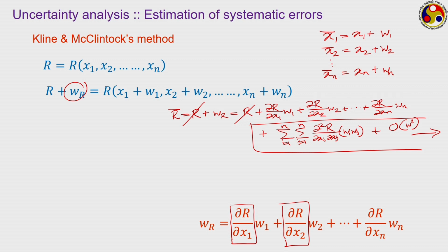Now, once we have done this mathematical exercise, how can we get the maximum possible error that can come in? Each of these terms, the product of sensitivity and corresponding uncertainty, gives a measure of how much maximum error the concerned variable can impart. Like variable number 2, the maximum error it can impart is this particular quantity, the product of the corresponding sensitivity and its own uncertainty.